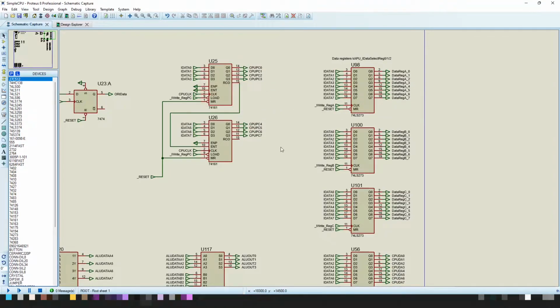We are also setting the CPU clock, and we also have the write register PC signal, and again it has to be held low for a clock signal before this will remember the data that is presented on the input. If it's high, it basically ignores what is on the input here, and it just continuously counts up from its internal state. It actually remembers the values.